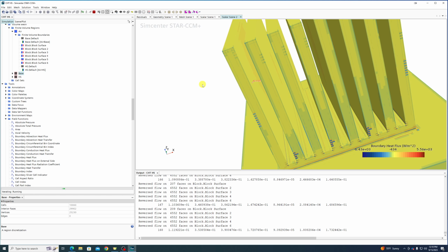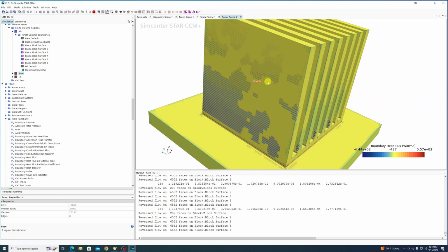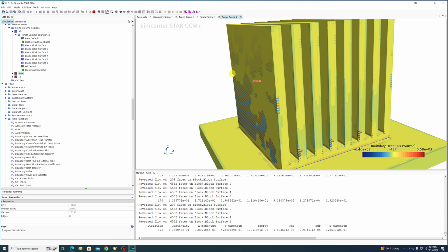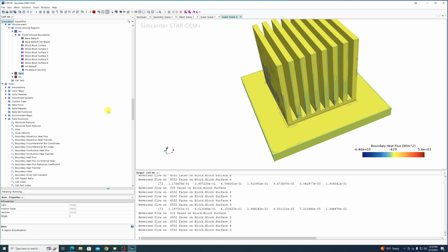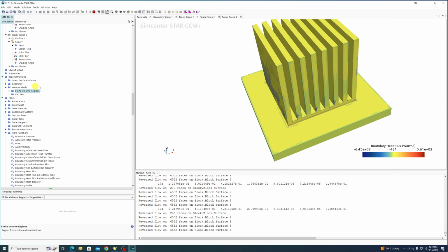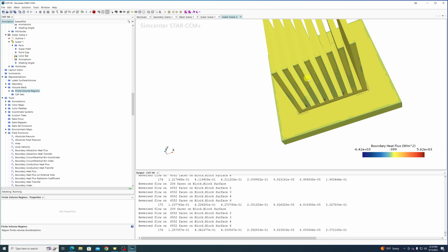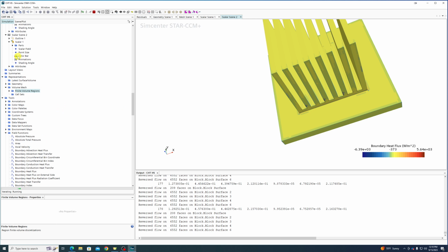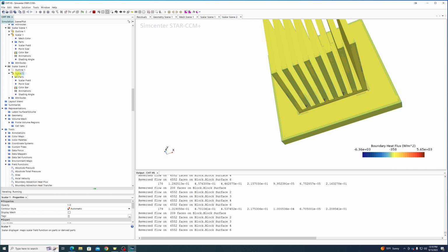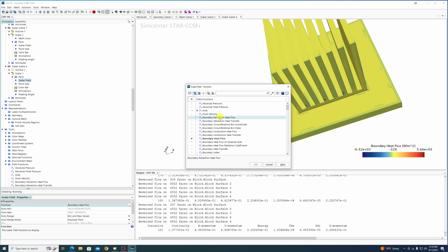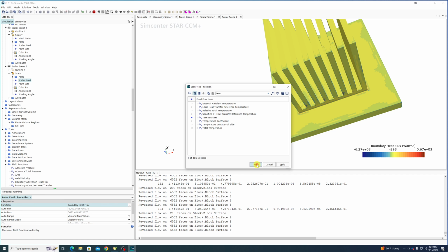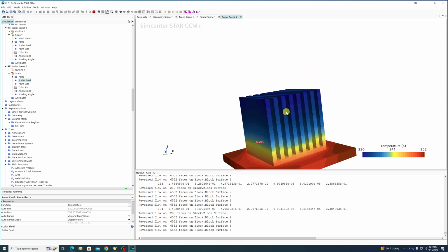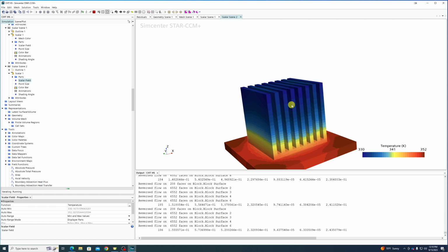Letting this run out some more might figure out what's going on, but this is probably going to take a long while to converge, so I'm not going to belabor the point too much. But you can look at the very same things in 3 dimensions as you would in 2. You can look at how heat transfer coefficient, temperature, heat flux, all these things vary with position over the body. Like if we just look at temperature, for example, we get this, right?